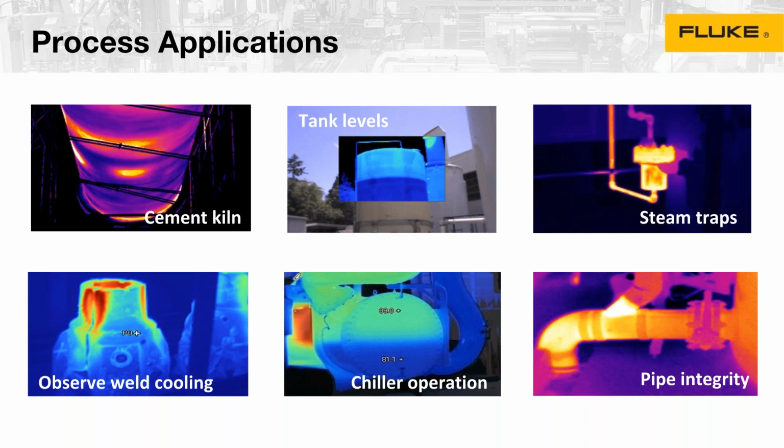And last, as I mentioned, is really pipe integrity. When you think of it, I never thought initially about looking at pipes, say, is there any blockage, any issue with the pipe? Why is there more heat coming from this particular pipe? And it could be a valve blockage. And valve blockage, for example, is very difficult to monitor unless you truly have a vision, or you have a flow measurement. They really indicate that you have a reduced flow or a different type of flow.